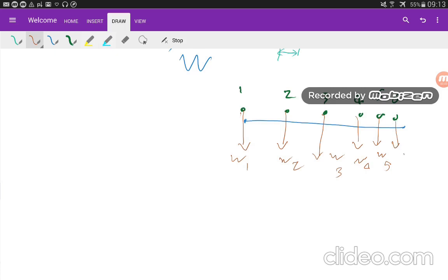Now, I have calculated with 6, but in a real vessel there are many more. So we have 6 cargo, and we want to find the center of gravity of this object. That's not easy to process with the simple previous method. What we need to know is the position of each cargo. Otherwise, we are not able to calculate the center of gravity.